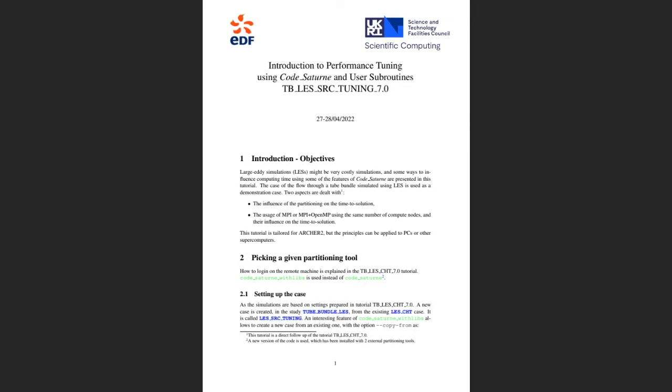First of all, and it is very, very important, don't use code_saturne to create your case, but use code_saturne with libs. The reason is that the version with libs has the partitioners installed in it, and the other one doesn't. So if you use code_saturne only, you cannot run the first part of the tutorial.